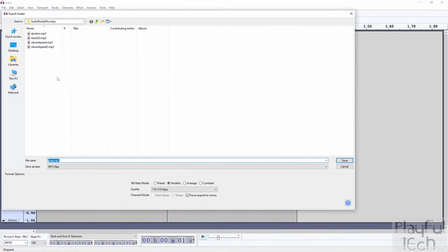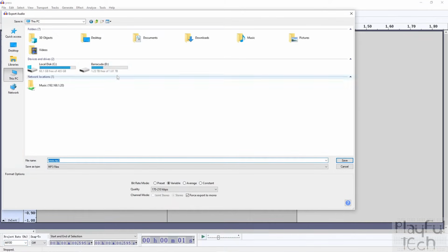what they will do is they will appear in your file explorer here just as another drive that you can save to. Now the important thing to note is the rules on how you name your file, and this is true for these boards that use the DY chip as well as the DF Player Mini, the Catalex, or the Arduino sound boards. In fact, every embedded audio module I've ever used uses these same rules.